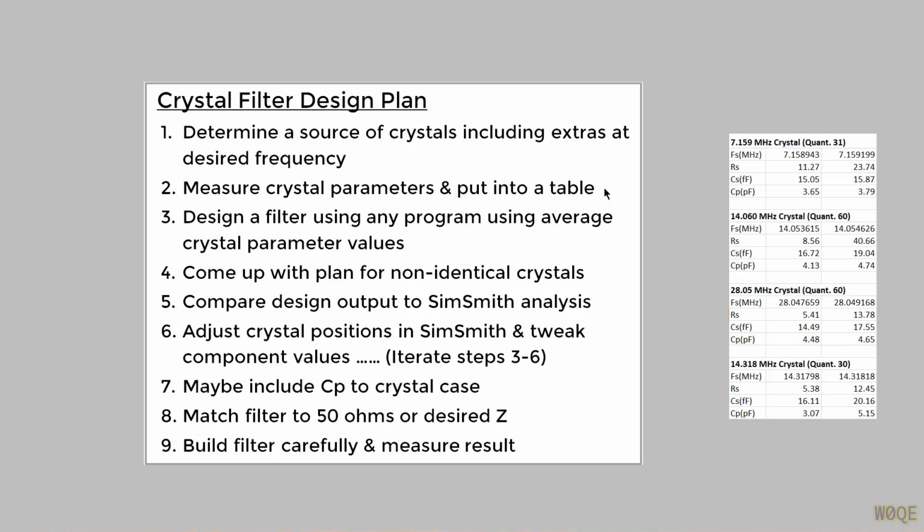As you get better, you really don't need to iterate much. And I can come up with some suggestions that will help you so that you put the crystals in the crystal filter in such a manner that you don't need to change the components very much. Then maybe we need to include the parallel capacitance to the crystal case in our design.